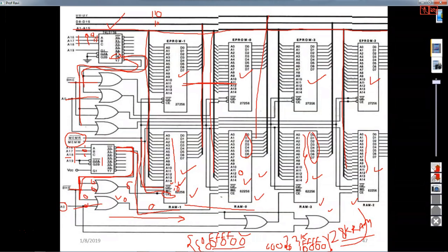Everything will be the same, the only thing is the mapping. Here the address would be A16 and so on. When it is 100 or all 00, Y0 and Y1 are selected. But when it is 110 or 111, Y6 and Y7 go low, and then chip select is made 0 along with your A0 and BHE bar using simple OR gates. The design logic here needs 4 OR gates, but there is no room, so two OR gates are drawn for this and two for this. When address is given to you, you have to be very clear in mentioning what exactly you are going to get.